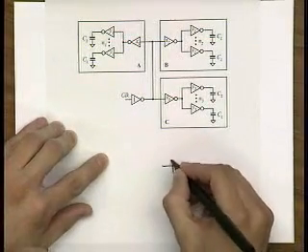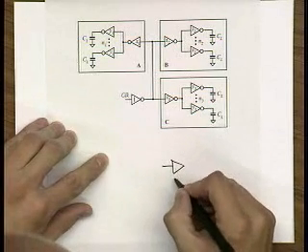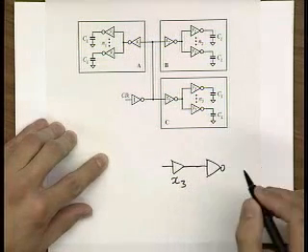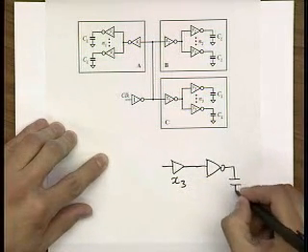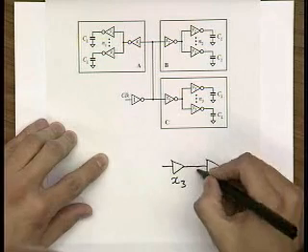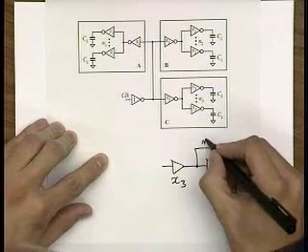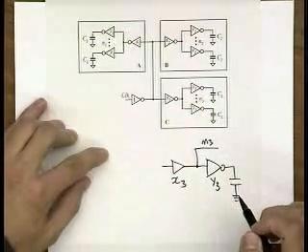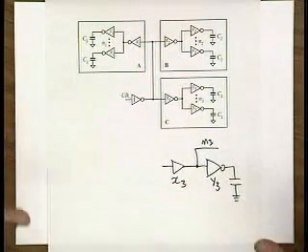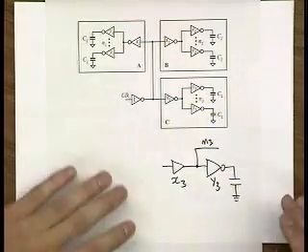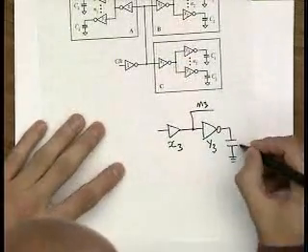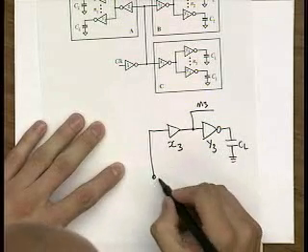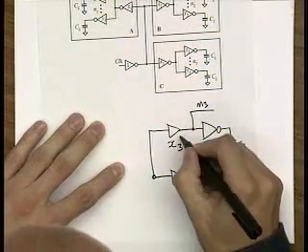So basically over here you have x3, and then you have this branching business that you're going to understand also later during today's lecture. You say that you have n3 identically sized buffers y3. That's just to develop a model for hand analysis. And then this is your load capacitance. And then you have the other two branches in the same way.